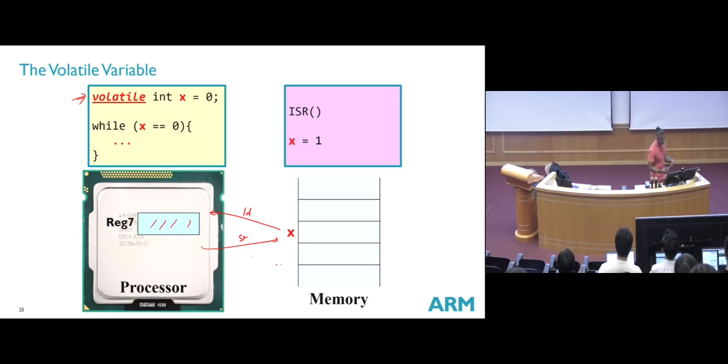Okay, which means that even if in the midst of the loop the interrupt is triggered, I will still get the updated value. Correct? Because the ISR will now update the value to the memory, and the loop will still get the latest value from the memory.